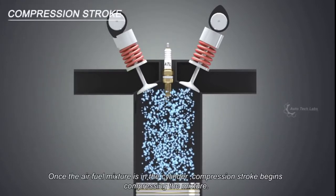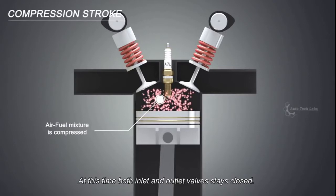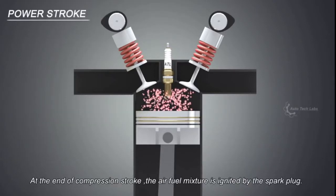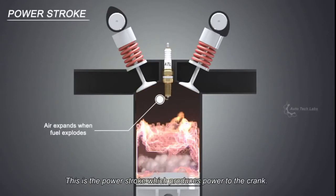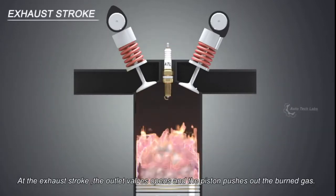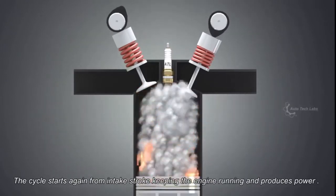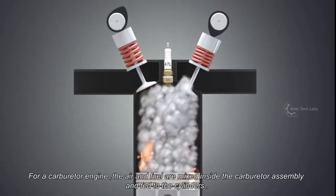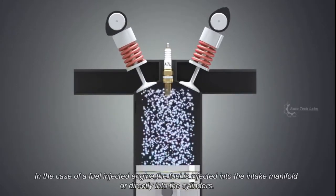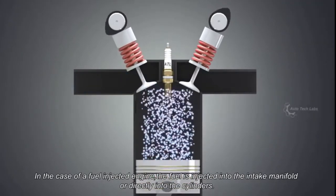Once the air-fuel mixture is in the cylinder, the compression stroke begins, compressing the mixture. At this time both inlet and outlet valves stay closed. At the end of the compression stroke, the air-fuel mixture is ignited by the spark plug. The explosion exerts pressure and pushes the piston down. This is the power stroke which produces power to the crank. At the exhaust stroke, the outlet valve opens and the piston pushes out the burned gas. The cycle starts again from the intake stroke, keeping the engine running and producing power. For a carburetor engine, the air and fuel are mixed inside the carburetor assembly and fed to the cylinders. In the case of a fuel-injected engine, the fuel is injected into the intake manifold, or directly into the cylinders.